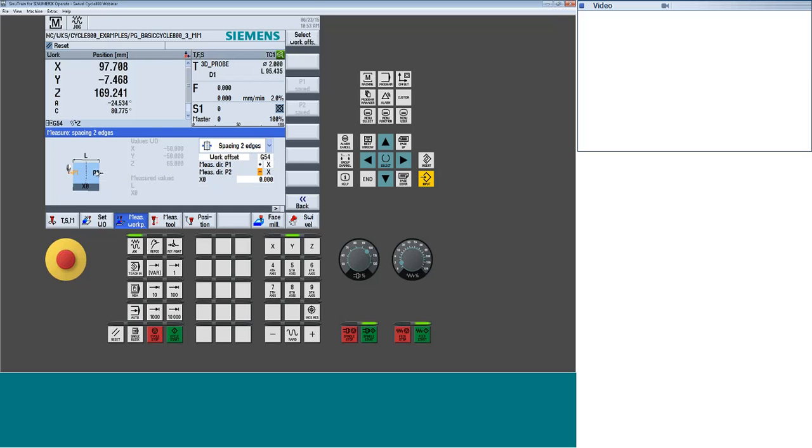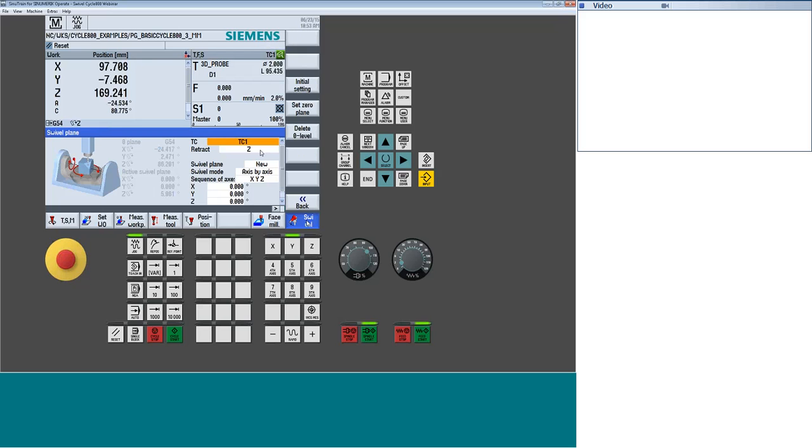Now from there, let's say I wanted to disable all of these offsets that are turned on. So what I can do is, if I want to cancel this tool carrier, I want to shut it off, say, hey, don't compensate for this motion anymore, I can do that through the swivel cycle by strictly selecting 0 and hitting cycle start. Now, the numbers change, but the machine didn't actually move. That's just a compensation value based on the 0. I'm still not sitting at 0, 0, but now everything's off.